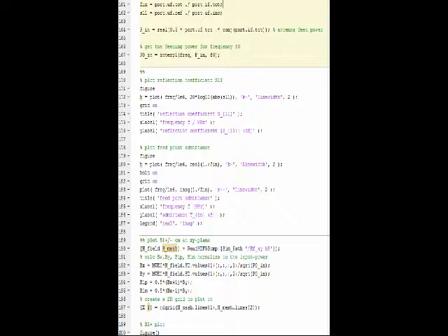P0 in refers to the feeding power for frequency F0. Therefore, we have F0 as a variable as input. For plotting the reflection coefficient S11, it was starting from 171. We create a figure, and then we plot the frequency in megahertz for the x direction, and in the y label, we have the reflection coefficient in the dB scale.